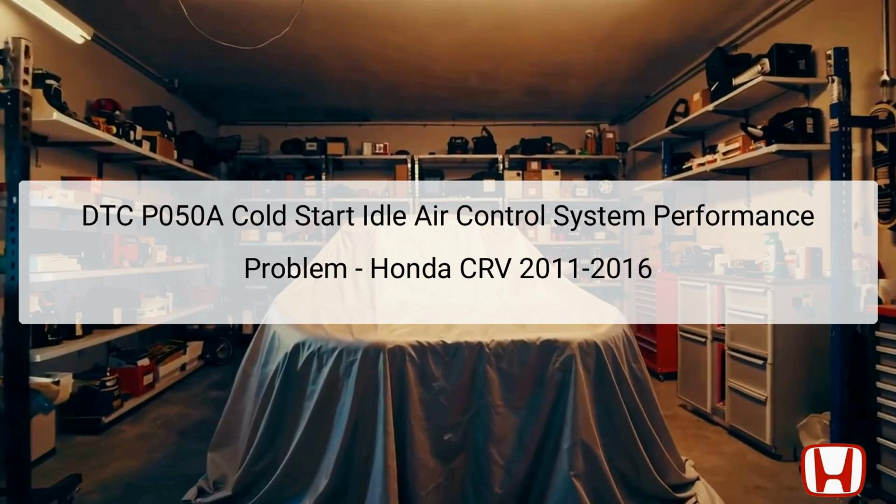The Diagnostic Trouble Code, DTC P050A, indicates a fault related to the cold start idle air control system in the Honda CRV models ranging from 2011 to 2016. This issue may arise due to several factors affecting the smooth operation of the vehicle's air intake systems during cold starts. The core components involved in this system include the electronic throttle control actuator, mass airflow (MAF) sensor, intake air temperature (IAT) sensor, and the powertrain control module (PCM).